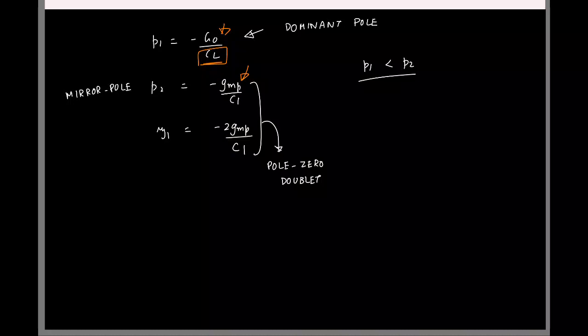Near to the origin, so if we got it pretty near to the origin, stability will be more dependent on that point. No, I mean, why is it dominant pole? Because the other pole will be far away, so it won't be contributing to the stability. No, but he mentioned time domain response, right? Let us assume that one pole is at minus 1, another one is at minus 100. If we take the response in time domain, it will come like e to the power minus 100 into t. Exactly.